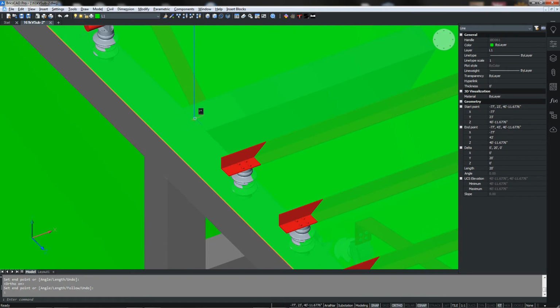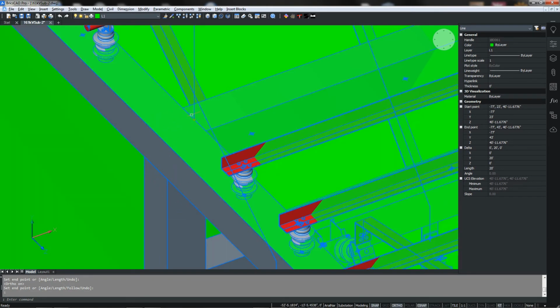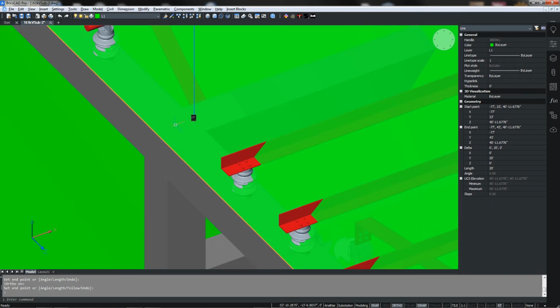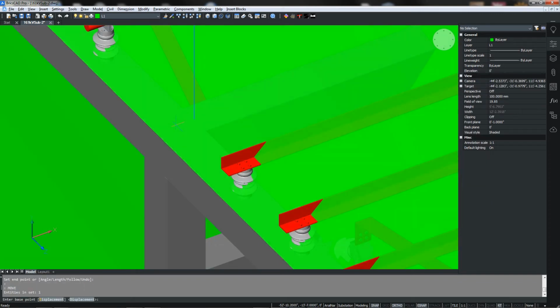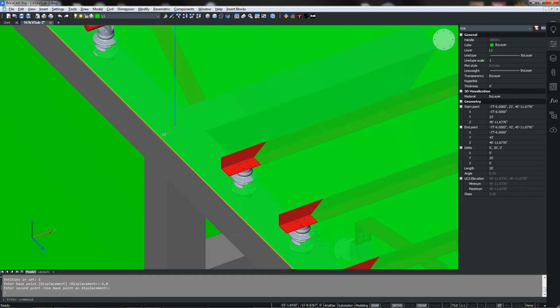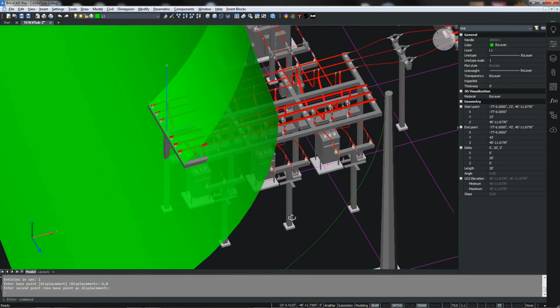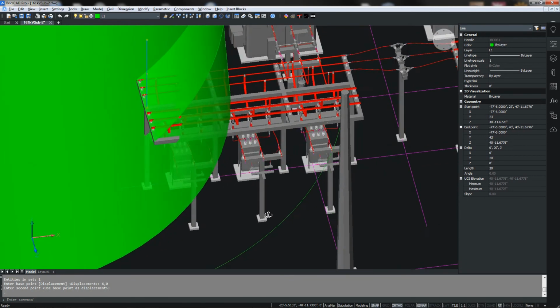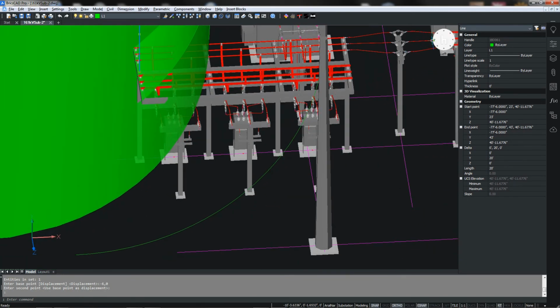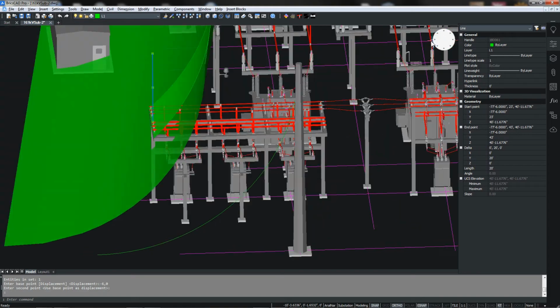And then the last thing I want to do is move this line over. I want it to be right in the center of this column, which means I need to move it over 6 inches. So I'm going to move that line. It's in the x-axis, so minus 6 inches, comma 0. And now we're right in the middle of this column, as you can see here. And what I'm doing here then is I'm going to use this as a lightning mast. So as a mast, we want to come back here.